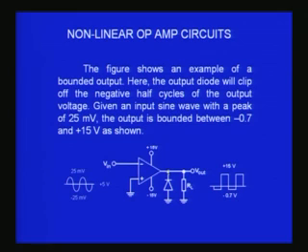When it becomes minus VCC, this diode will be forward biased, and therefore it will be conducting, and I will have only about 0.7 volts as the output voltage, which is the voltage produced across the diode. Therefore it is minus 0.7, because this voltage will be negative with reference to the ground, since the current is flowing in the other direction.